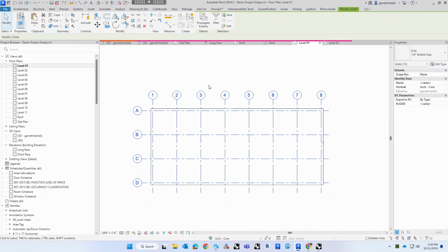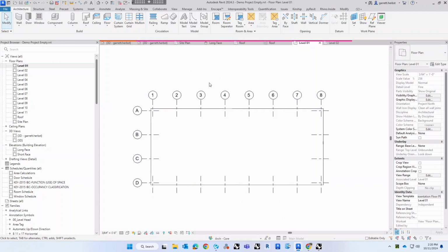That's another thing too, not only for your structural grid, but also as you're starting to design your facade system and start to set up potentially the exoskeleton for your facade, you'll probably want to create multiple conceptual masses that have different offsets of the mass so that each of those elements are associated with the correct depth from each other. So like in the original model that I had up there, the exoskeleton and the curtain wall system are in the same exact plane, which doesn't actually work. You can offset them from that plane, but then the corners get all weird and it doesn't work very well.